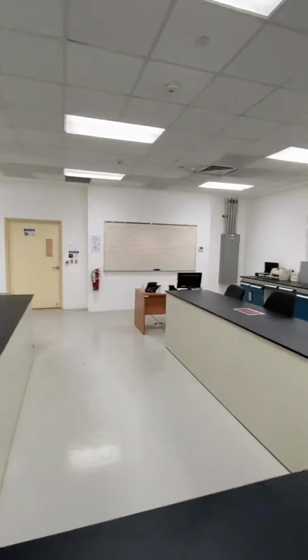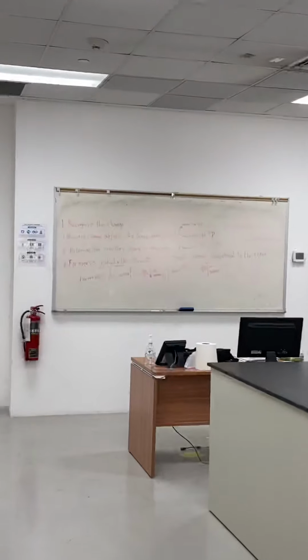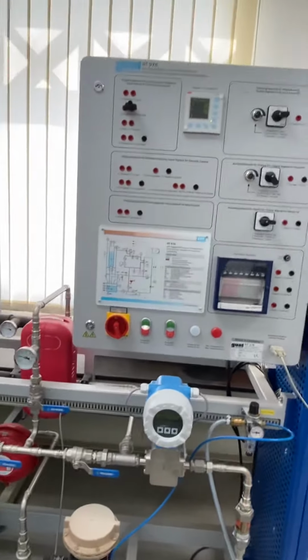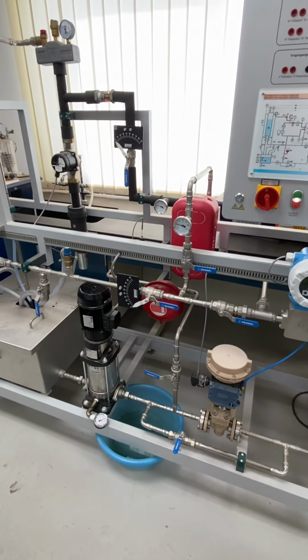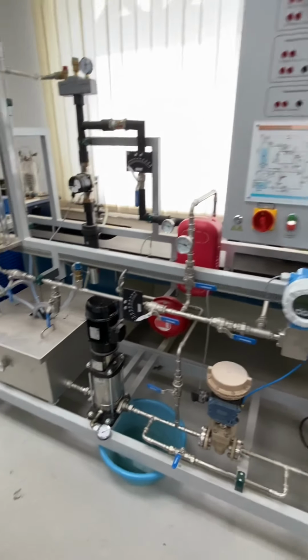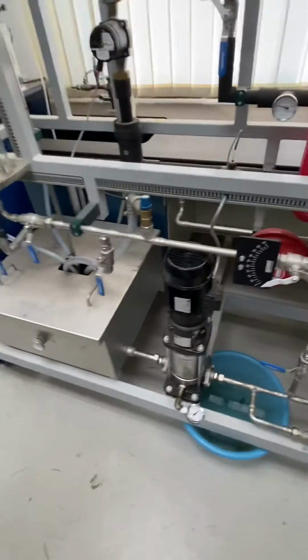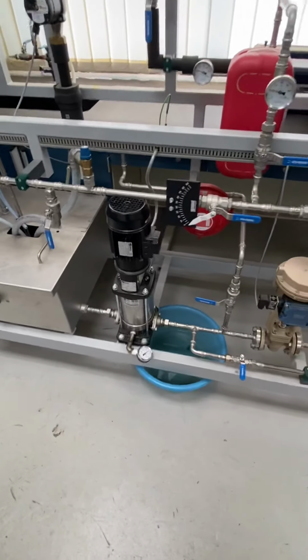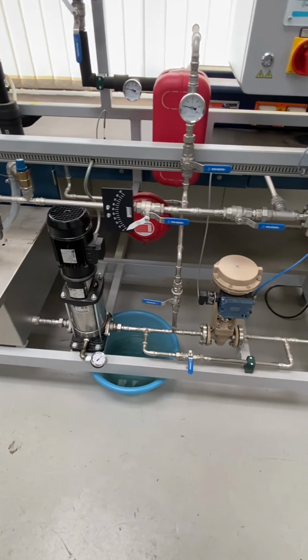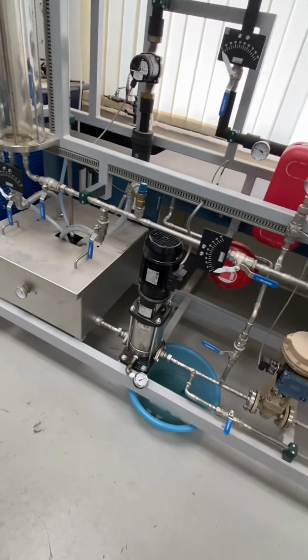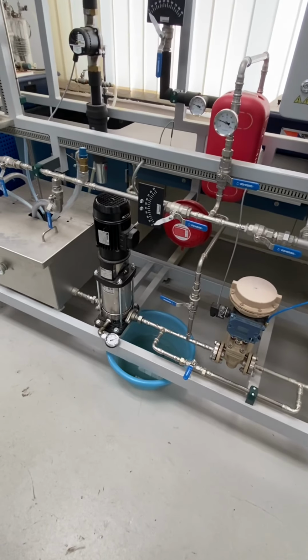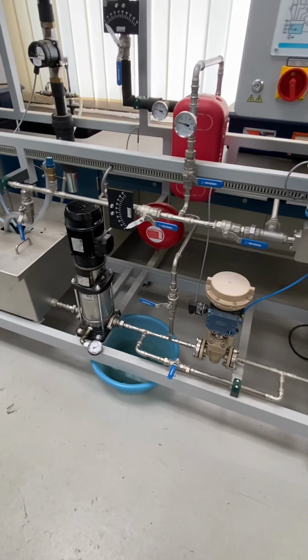Okay, all right, so for recognizing the change, which is the first step over there, we need to know what's going to happen when P1 speed gets below the normal speed. It is very simple, actually. Once you reduce pump speed, you will notice that the flow rate will decrease, because reducing the speed of the impeller will definitely reduce the flow rate through the system.